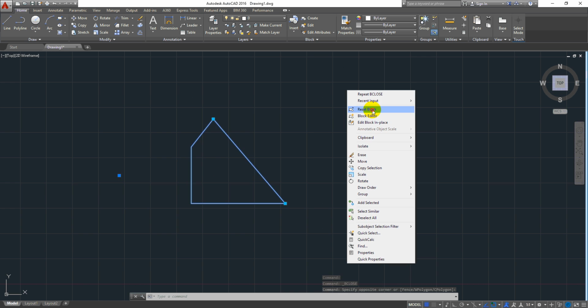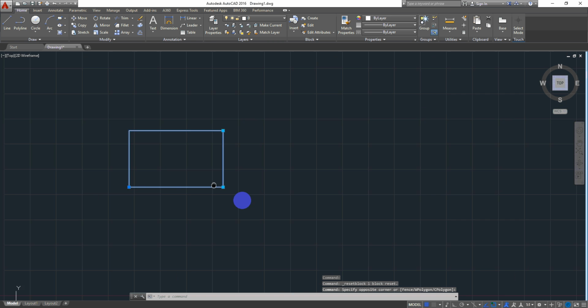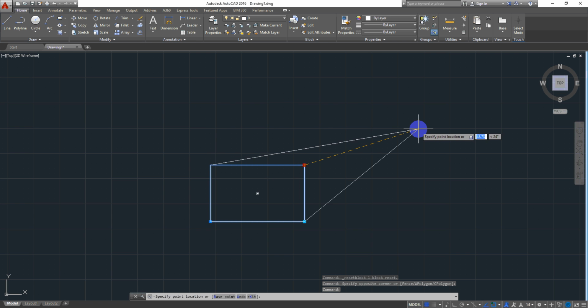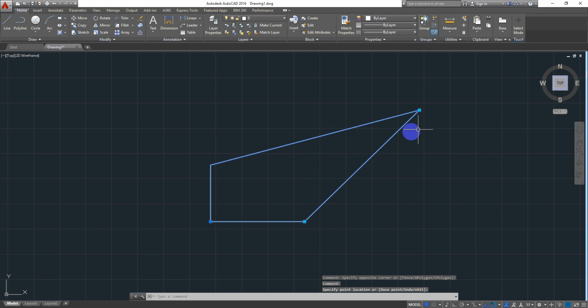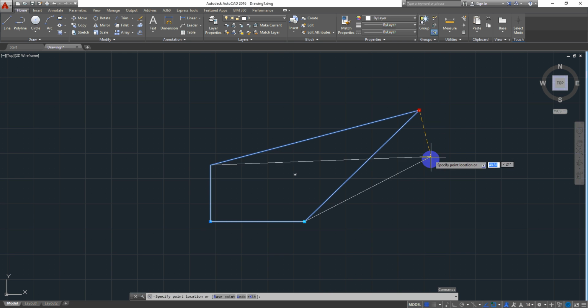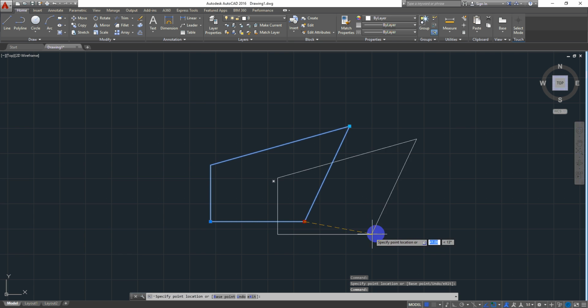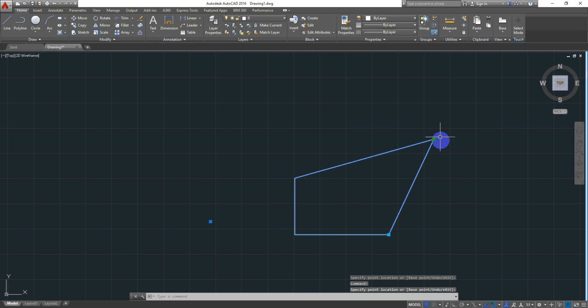Now reset the block to make it go back to the previous position or shape. Now if you click this grip and drag it, you can see within the block I can drag this rectangle. That corner, whatever I have selected using that window, that much portion of the rectangle is getting stretched. Now if I am moving this, it is moving along with that.